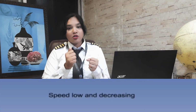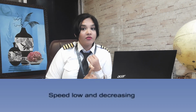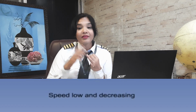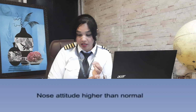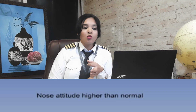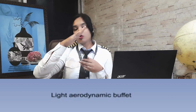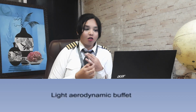When the flight controls become less effective, that's the first sign that stall is approaching. Second, speed is low and decreasing. Third, nose attitude is higher than normal: the nose of the aircraft pitches up and will be higher than normal.